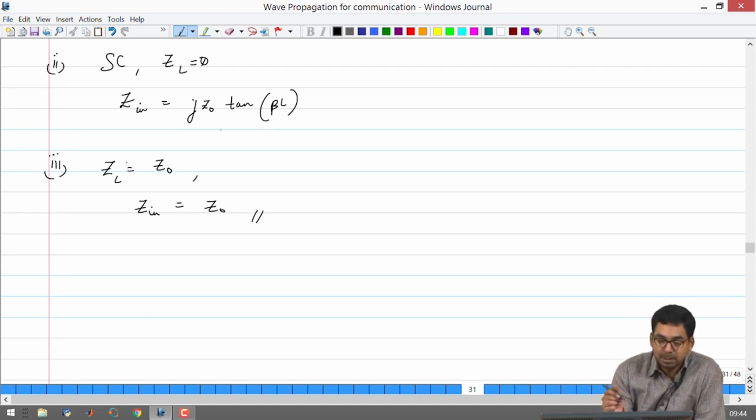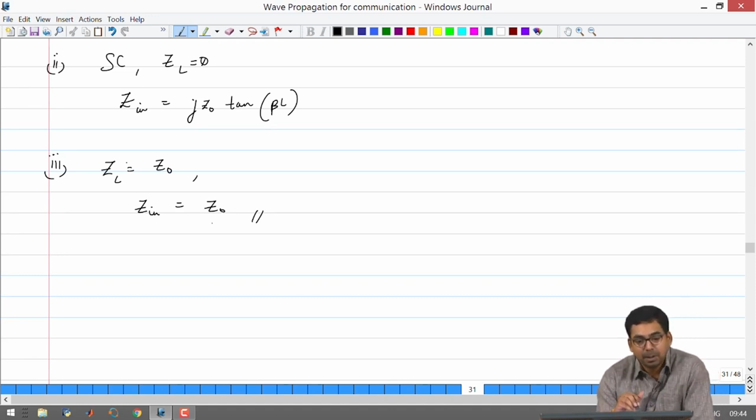So, this means that I now know how to create different impedance profiles by making use of this. Suppose I wanted to manufacture a high frequency circuit, I could make use of these properties to replace some inductors, some capacitors, some combination of inductors and capacitors, and I could also target some specific values of Z in equal to Z naught to fill up some purely resistive branches of your circuit. But this is not very convincing because although we have made L and C very easy, resistance is not something that is coming into the picture.